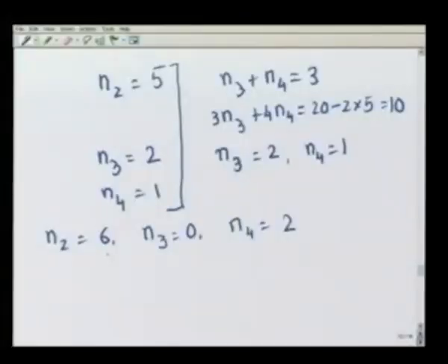That means we can have an 8-link mechanism with 6 binary links and 2 quaternary links. Now, from these 3 different types of 8-link chains, by kinematic inversion, one can get a very large number of different mechanisms.